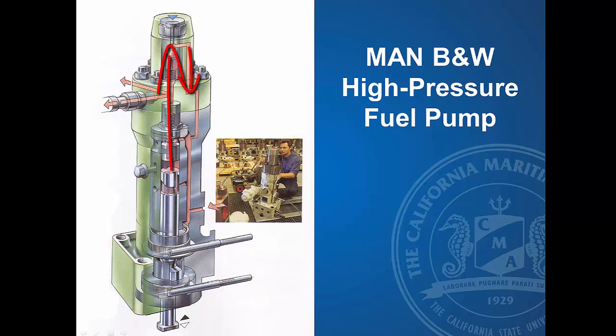So in other words, if active delivery is ongoing, no matter where the port helix is, that puncture valve opening up that check means the contents of the barrel will spill right back to the suction, ending delivery. Now, this is used for emergency shutdown, but it's also used each time the engine goes to start.